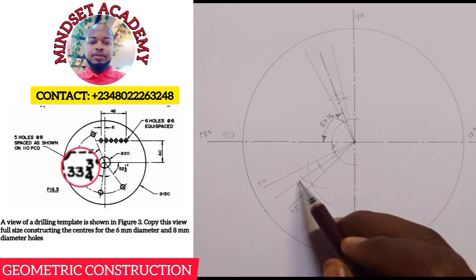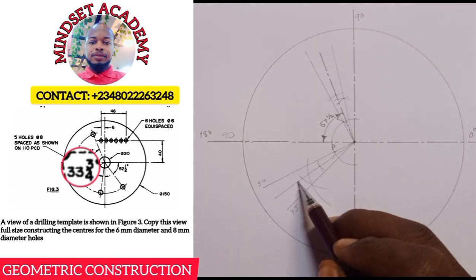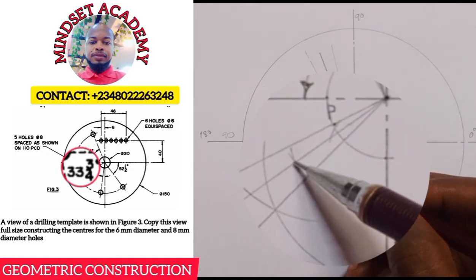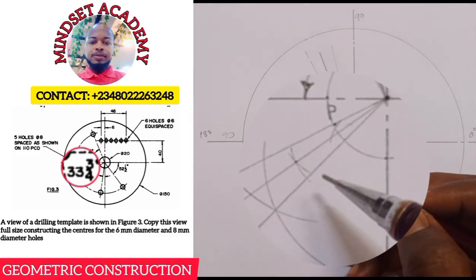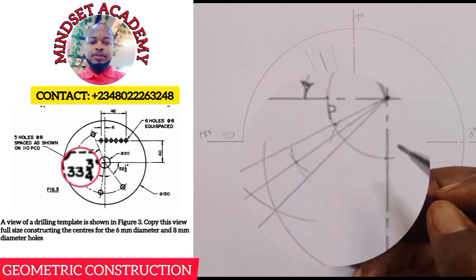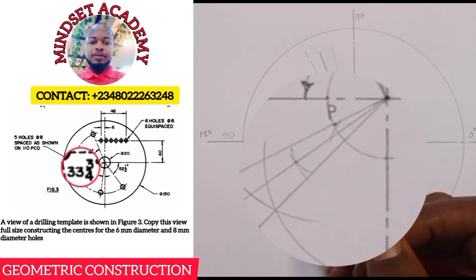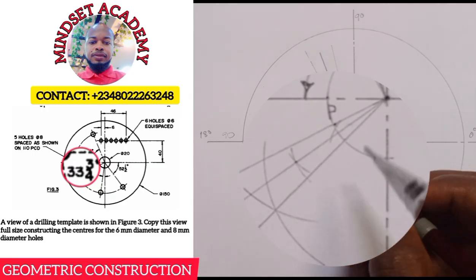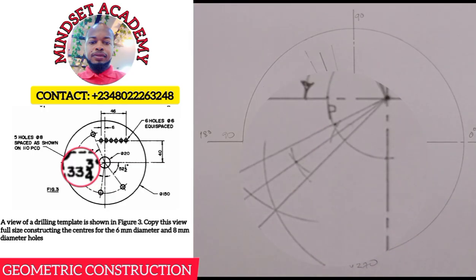This first half is 7.5. This next half is another 7.5. We're moving towards this side. So that means if I now bisect these two lines here, because bisect means dividing by 2, 7.5 divided by 2 gives us what? That'll give us 3.75, right? So I'll bisect that.